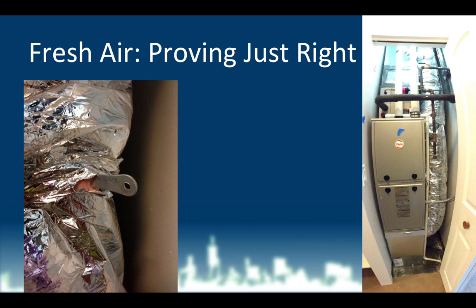But I have to test this thing and get it set to the right amount because there's a damper, essentially another flap inside of this, that's manually set so that we bring in just the right amount of air. We don't want too much, we don't want too little, we want the right amount of fresh air without giving an energy penalty. So this is a handle that someone very nicely has shown to me by poking it out through the insulation. I love that. However, not all of these have handles in the first place, and not all of them are sticking out already, so I have to go in there and find it.